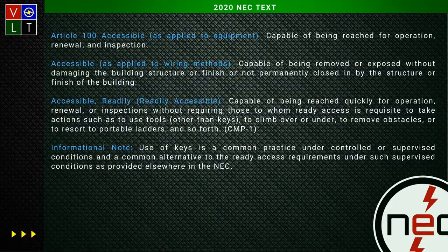Is there anything else you'd like to add to it? Well, I had a job that I did, and it was in two different districts. One was the city of Boulder, and the other one was the city of Longmont. I put both GFIs underneath the cabinet, over towards the side and up high, so you could get to them real easy. I did them both exactly the same. I had one inspector say it was fine, and the other inspector say I want it moved. It really wasn't a big deal to just move it above the sink and change it around a little. I think it took me like 10 minutes to fix it.